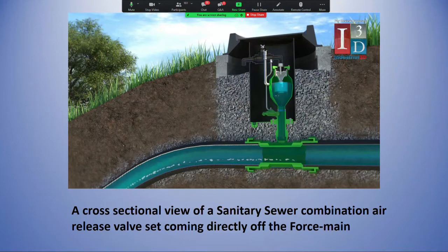We're going to have a better connection to the valve. But more importantly, any kind of vacuum that's acting on that valve is also going to back flush itself and clean it out. Whereas a lateral is typically going to have a much smaller diameter pipe coming into it, and it's going to be very difficult for any kind of backflow or vacuum to work itself through that lateral should it get plugged or compromised due to grease accumulation or solids.